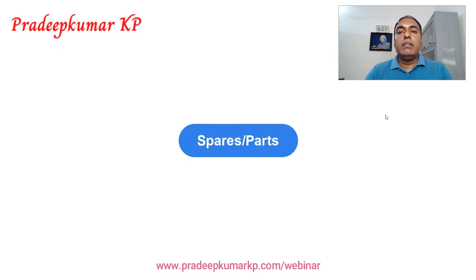And the fourth one is that we should have the knowledge of the spares and parts, what all spares are fitted. We must know the spares' make and parameters also, like what kind of axis motor has been used, what kind of spindle motor has been used, what kind of transmission system, whether it is ball screw, lead screw, or rack and pinion, and what is the make of those parts. We must know all these things.